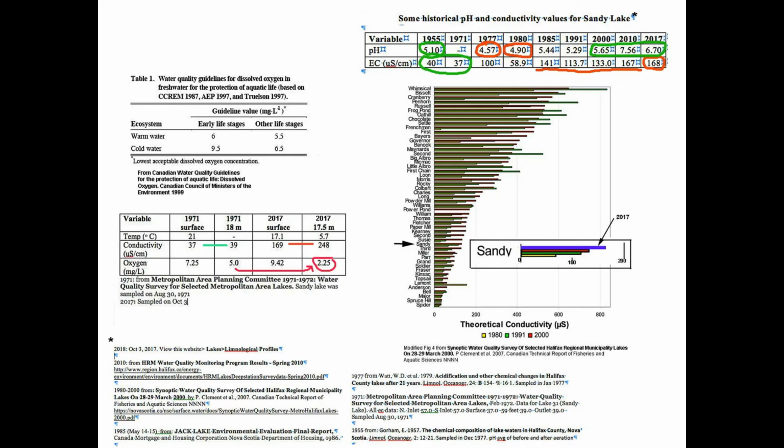And this kind of integrates some of the different measurements. So first of all, oxygen. How much oxygen do we need? This just shows you the oxygen requirements for protection of aquatic life, for warm water life and cold water life. These are the salmonids, these are the other types of fish species. These ones need more oxygen than the other ones, and it shows you the critical values.